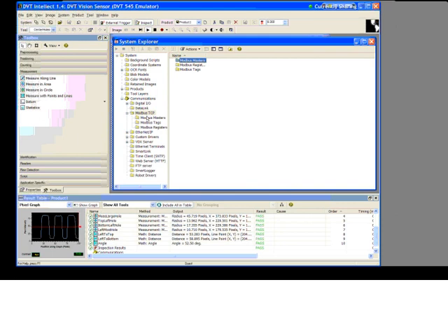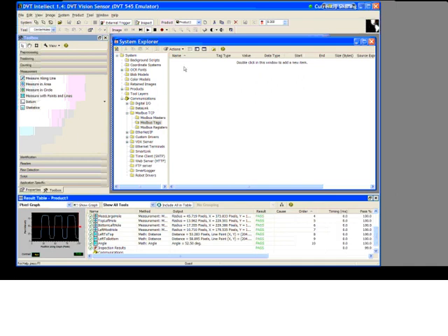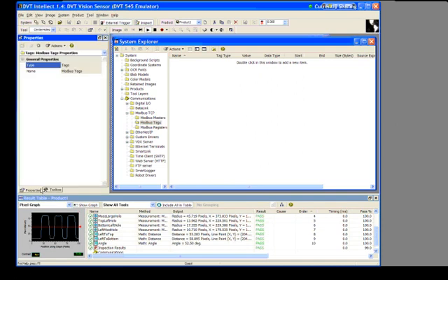Here the OPC configurator is the master, so I don't need to configure anything under the Modbus master's interface. I just need to provide those values through Modbus to the OPC server. I can do that through scripting functions or by just creating tags on the Modbus register space.